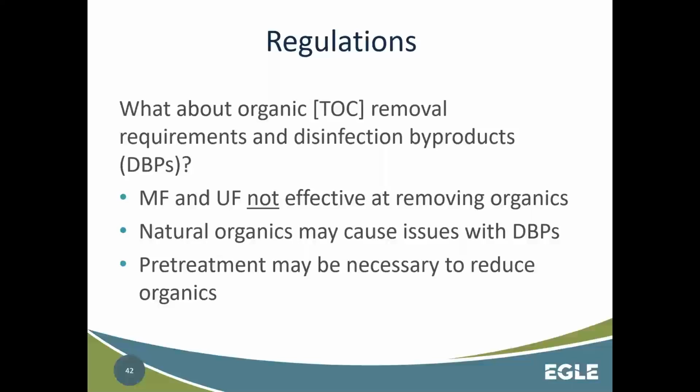So again, we do have a couple of membrane plants in the state that are challenged with disinfection byproducts. They have to perhaps manage their distribution systems more carefully. They might have to do some aeration in their water towers. They may have to be very careful with their dosing of their disinfectant to try to keep that under control. So I am going to stop there.